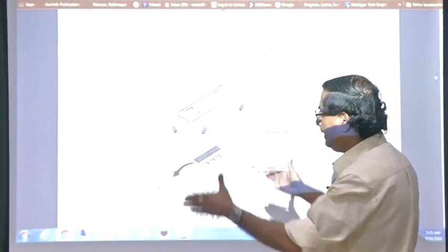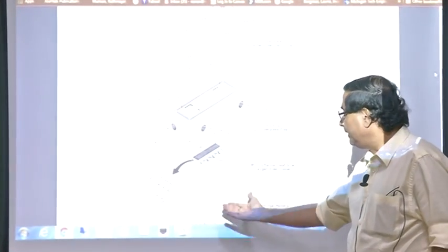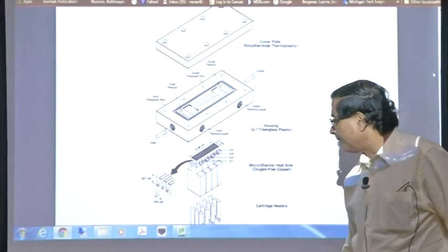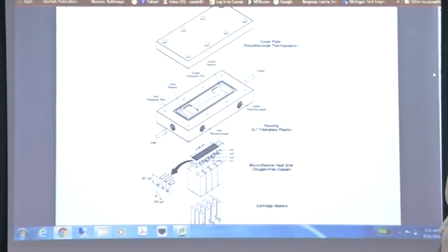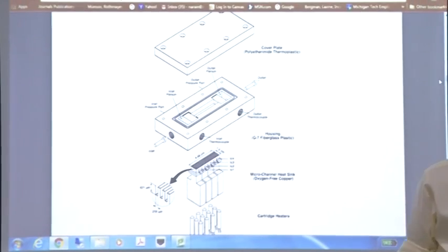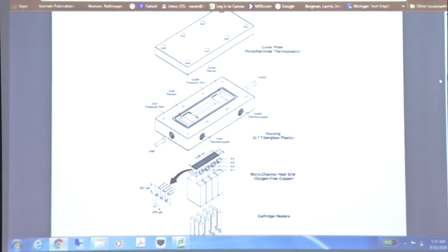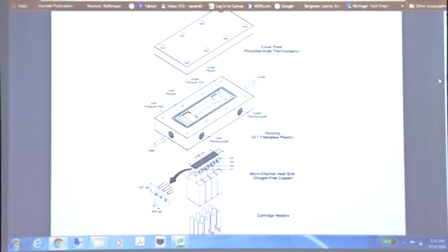Typical, like in this particular experiment, somebody was asking about, in this particular experiment, the high heat flux is arranged in a channel which is 3-sided heating, and electric heating is coming from the bottom. You can put, to create a large amount of heat, like 400 watt per centimeter. This is one of the cheaper ways to do it. It's very hard to have a thin film and have it at that high level.